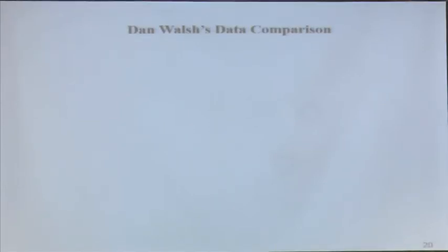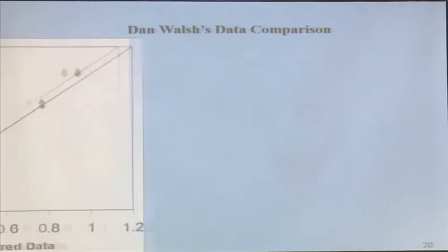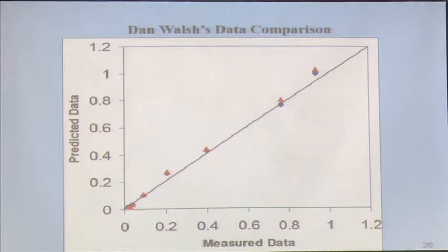Now I am comparing the measured data with these two different models, two different approaches, Cliff's method, the iteration method, and Concha and Almendra's method. And what I have seen, comparing your measured data and the predicted data from these two systems, is that Cliff's method gave me 11% error at 95% confidence interval.